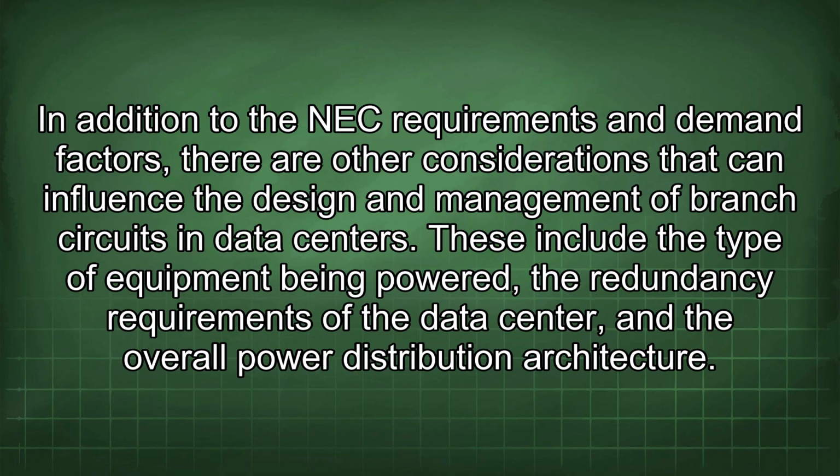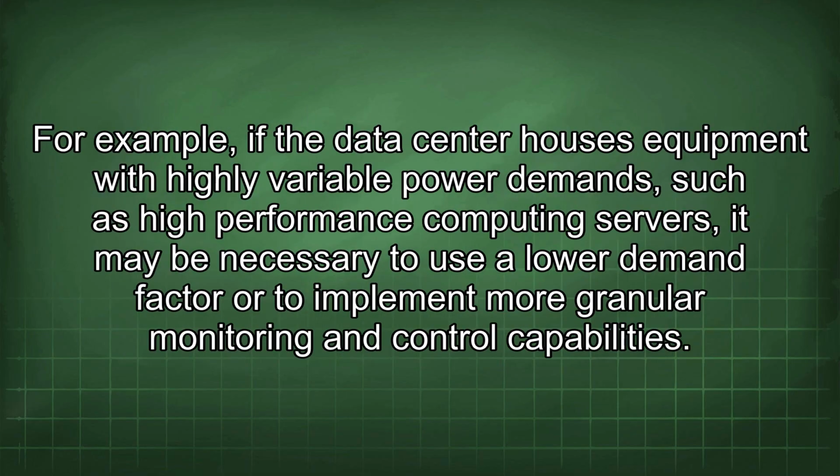In addition to the NEC requirements and demand factors, there are other considerations that can influence the design and management of branch circuits in data centers. These include the type of equipment being powered, the redundancy requirements of the data center, and the overall power distribution architecture. For example, if the data center houses equipment with highly variable power demands, such as high-performance computing servers, it may be necessary to use a lower demand factor or to implement more granular monitoring and control capabilities.